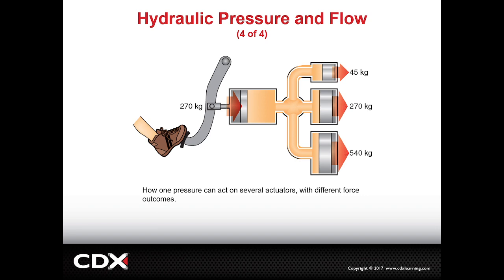So that's like a shortcut. There are calculations in every situation, but when you have these force factors, you can look at, for instance, the distance traveled. If you have a 2 to 1 force factor, and you push it down 10 inches, you're actually only going to move 5 inches at the actuator. So you're going to lose distance by doubling your force. You're going to cut your distance in half. And that applies in all of the situations. So moving on.